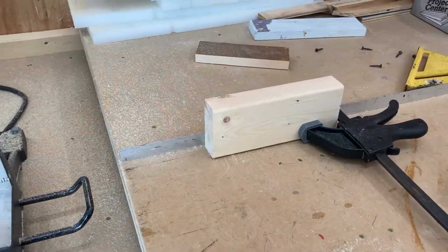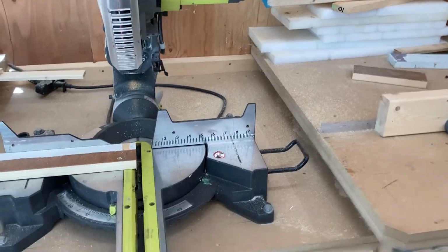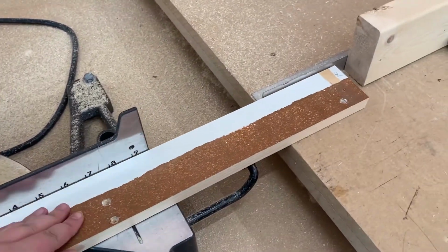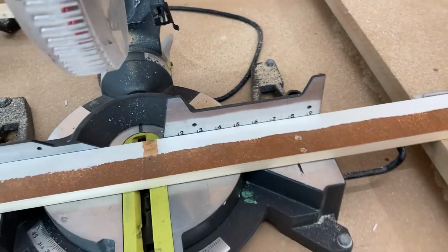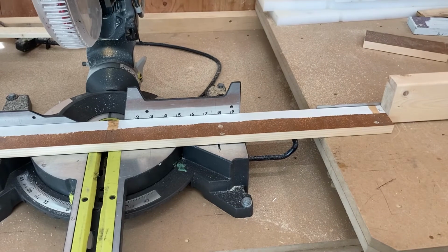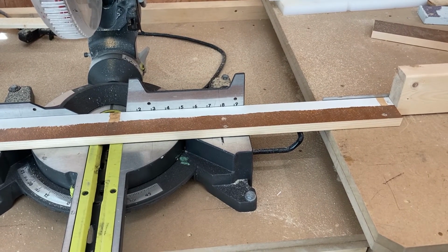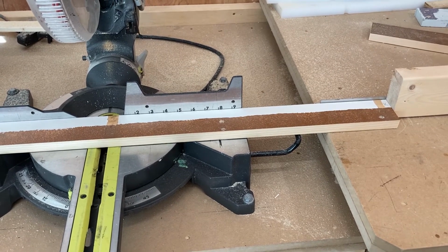I've set this block 1 foot 8 3/4 away from the blade so that when I push the material in, it'll be gentle, because if I knock it hard, it'll move. But I can push material in and I can know pretty reliably that if I cut, even without measuring there, it's gonna be 1 foot 8 3/4. And I can do repeated cuts over and over and over, skipping the measuring portion and save some time.